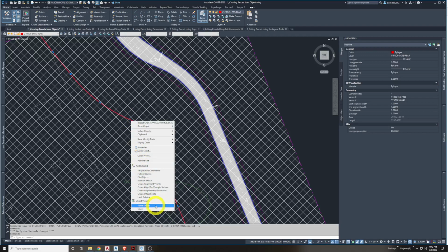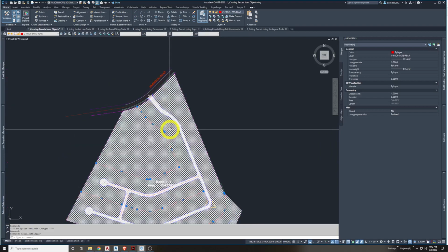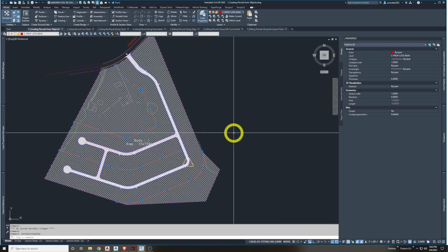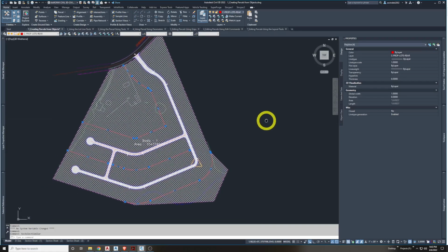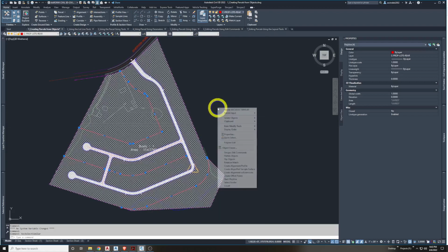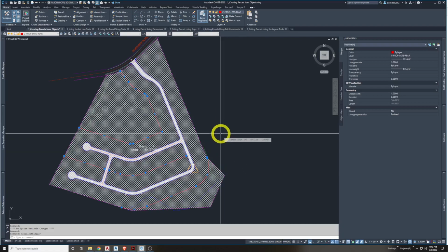This is a way to select anything of a very similar property and layer. So it selects all polylines of that layer, basically, and that's select similar. It's a smart command I use a lot when I have things segregated by layers and type of object. In this case, similar polylines on the same layer. So at this point, we have them pre-selected.